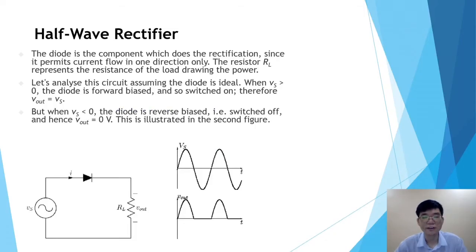There are several types of rectifier, but today we will talk about two types: the half-wave rectifier and the full-wave rectifier. A half-wave rectifier is defined as a type of rectifier that only allows one half cycle of an AC voltage waveform to pass, blocking the other half cycle. Half-wave rectifiers are used to convert AC voltage to DC voltage and only require a single diode to construct.